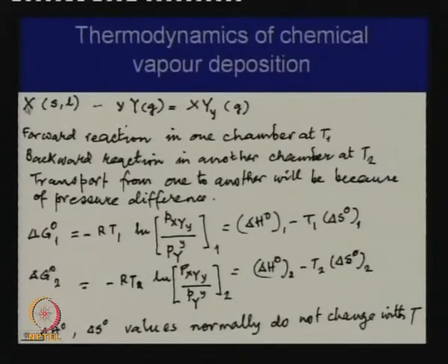that we can take an impure metal, make it react with a gas phase to produce a second gas phase at one temperature, then decompose that gas phase at another temperature to produce pure metal. So, take impure metal, react with a gas phase, produce an intermediate gas, take it out, then sometimes at a higher temperature decompose it, sometimes at a lower temperature it will produce a purer metal.